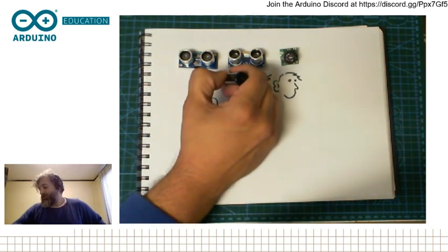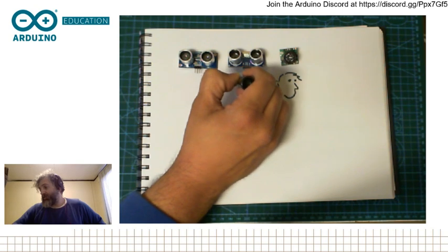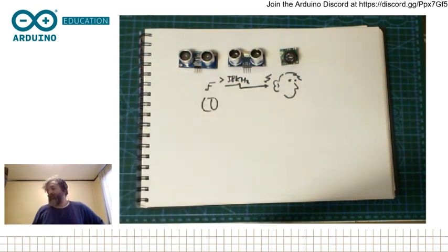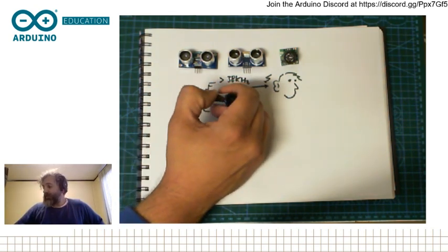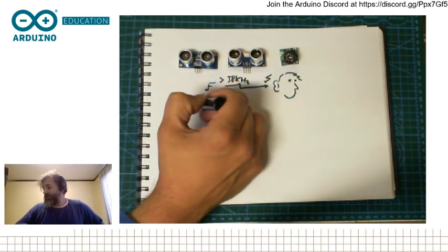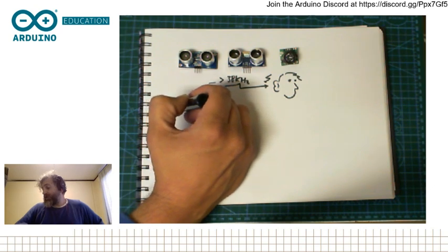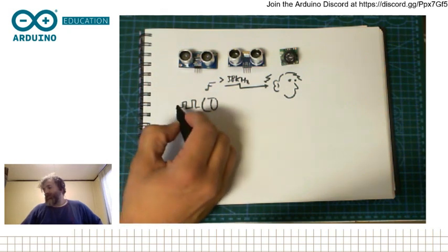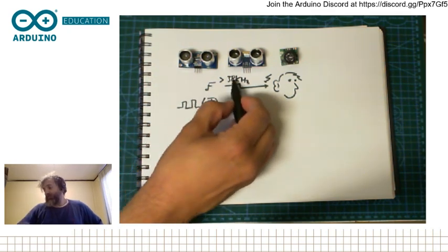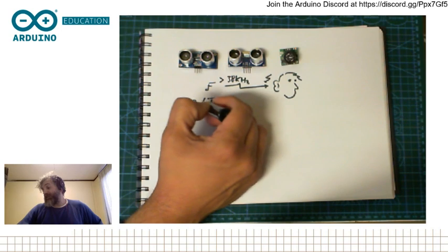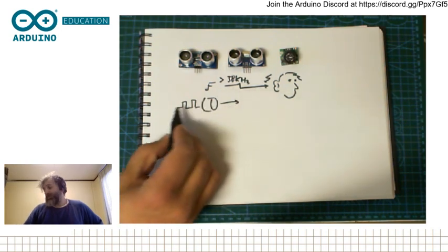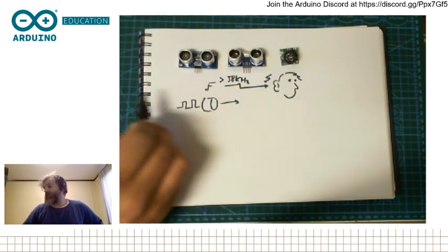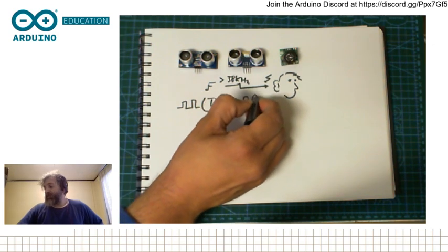It's over typically 38 kilohertz or more. 38, 40, 60 kilohertz, whatever. And the idea is that these transceivers optimize when they get a train of pulses in a certain frequency, which is oscillated at a certain frequency, they translate this to the air. So they get a digital signal and they oscillate, and then they send this through the air.